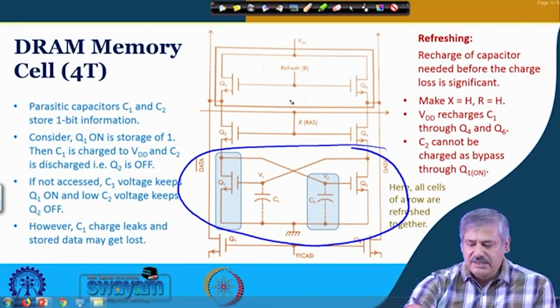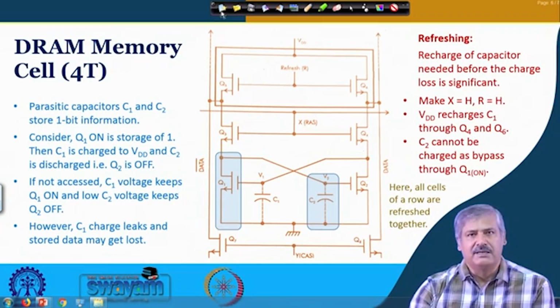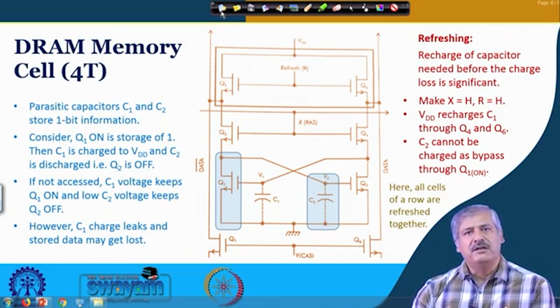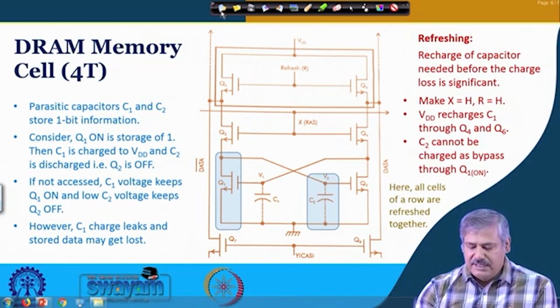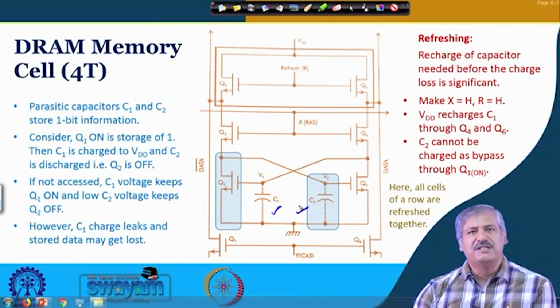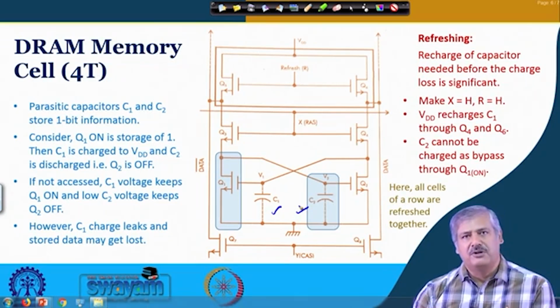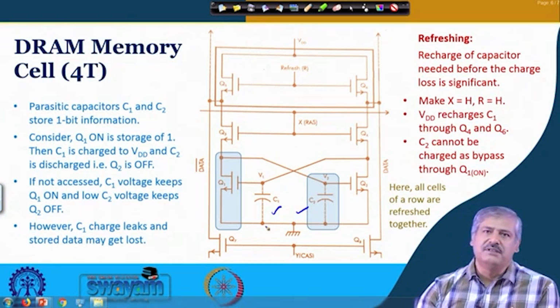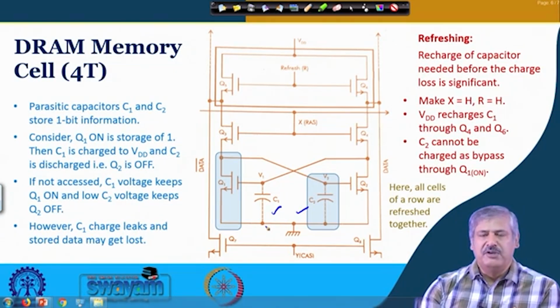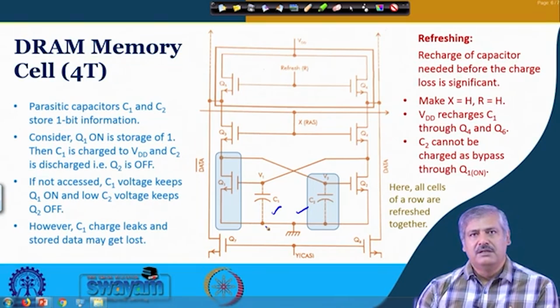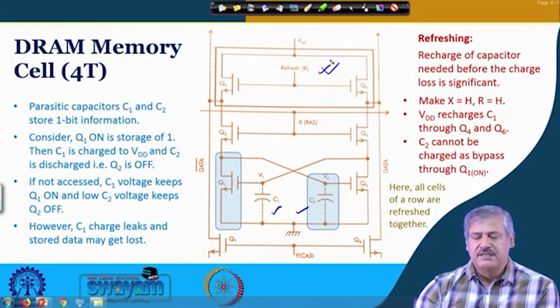In this case, those load transistors are not there holding the cross coupled inverter in one particular state value. Rather, the capacitances that can store charge for a short time are used. Of course, as we have noted, even when the memory is not read or written into, it needs to be refreshed, for which separate refresh lines are associated.